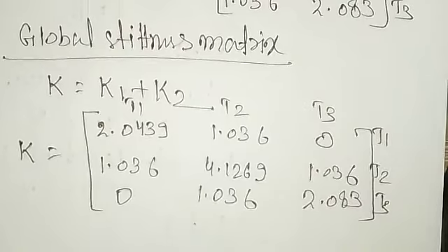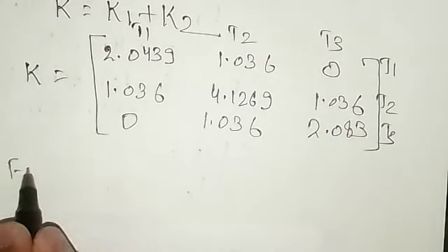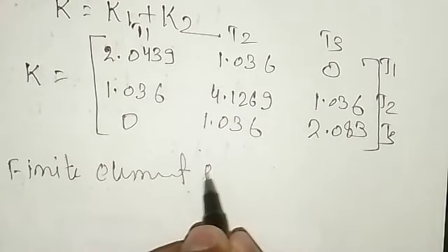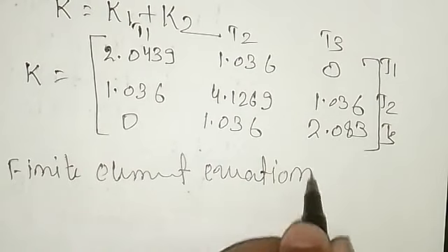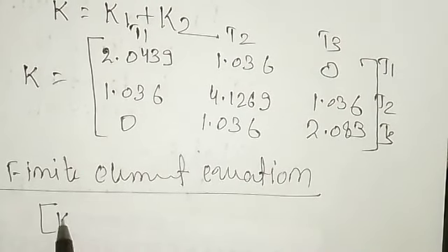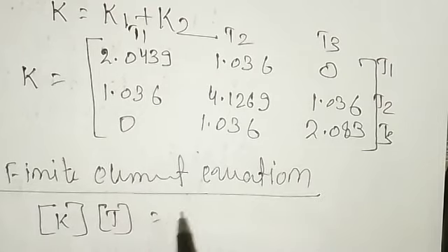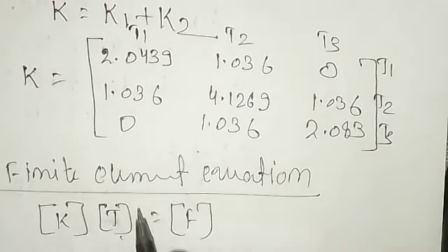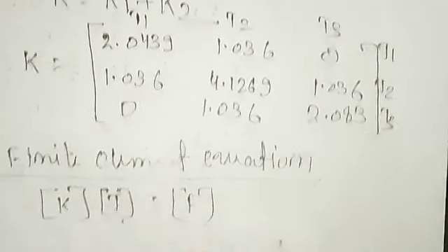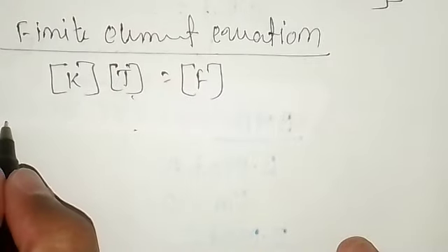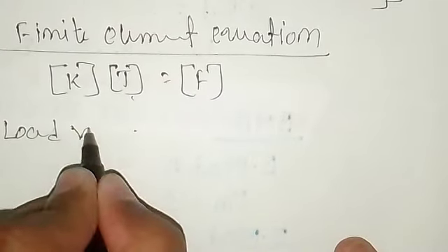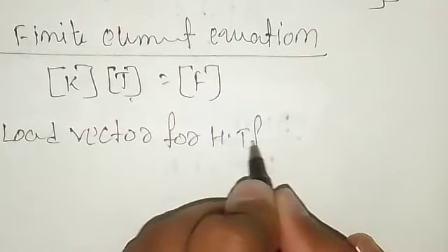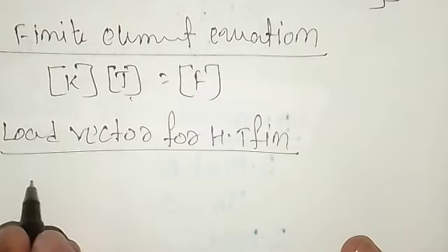Now we need to import the finite element equation. So finite element equation is what? K T is equal to F. So K we already calculated. T means T1, T2, T3, nodal temperature. F load vector we have to calculate, right? So first we'll calculate the load vector for the fin problem, right? So load vector for heat transfer fin, right? So load vector is equal to what?